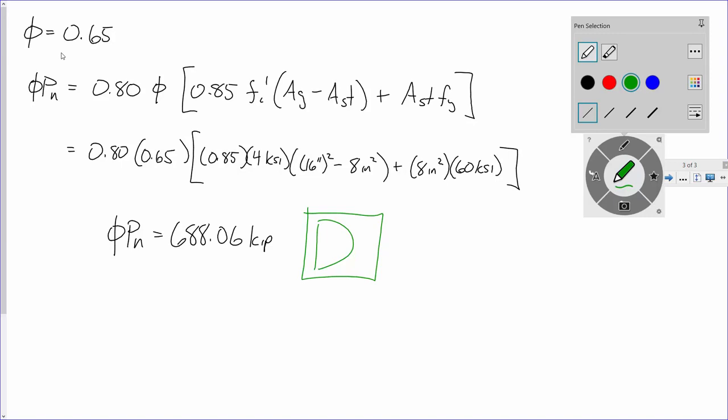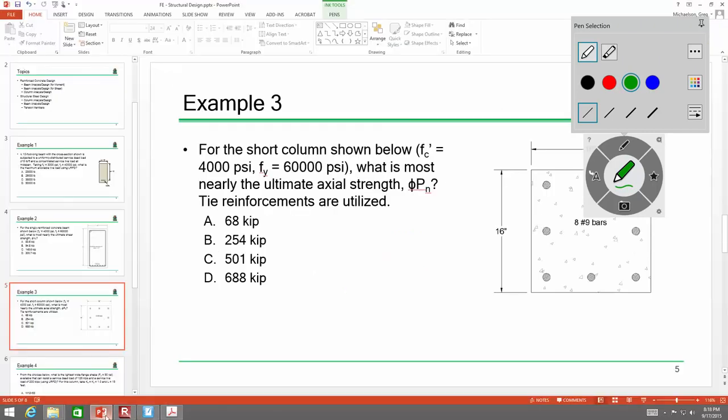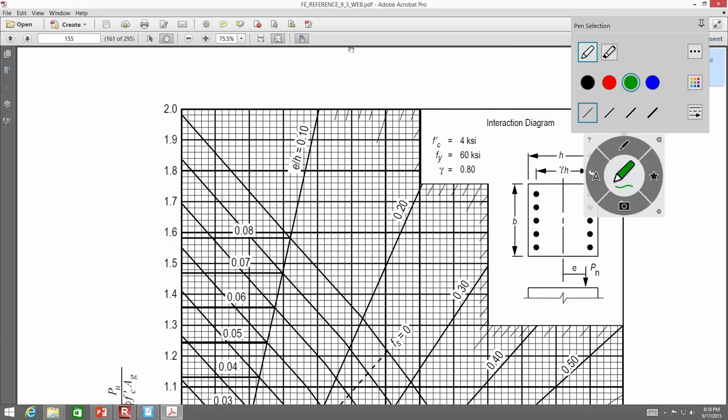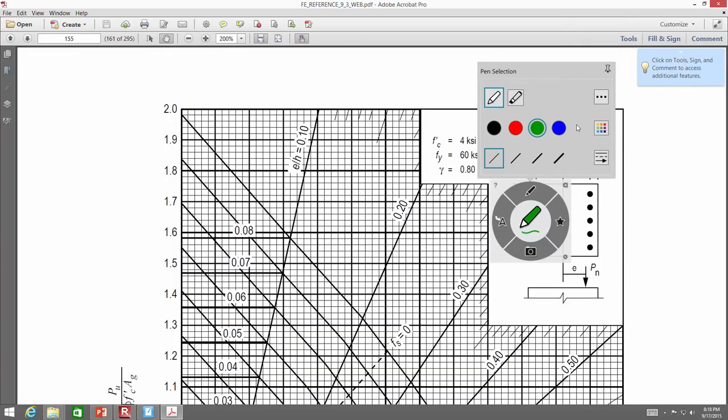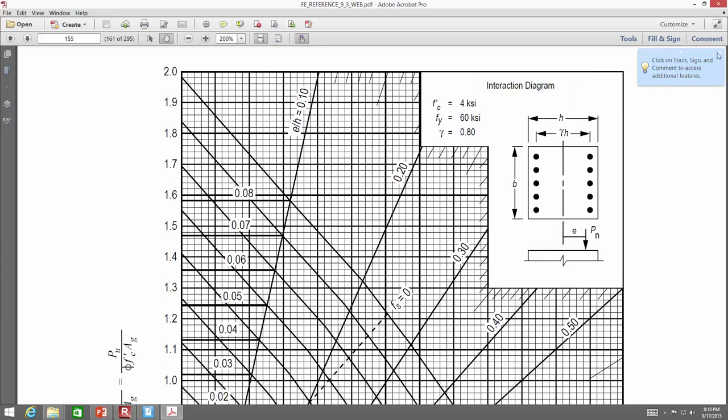Everybody good? All right. So here's what's going on with the beam column problem, and I might throw this in next year's review. Here's your beam column interaction chart. If you remember, these are basically just P-M curves for different beam columns of different dimensions. So you can't do a beam column problem on the exam if they don't meet these specific dimensions.